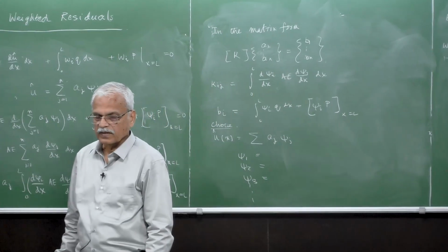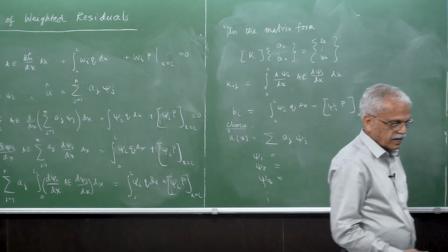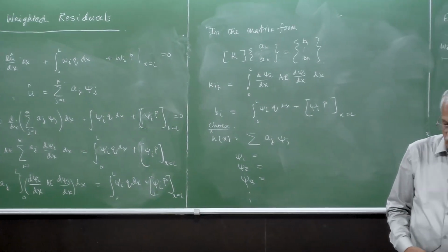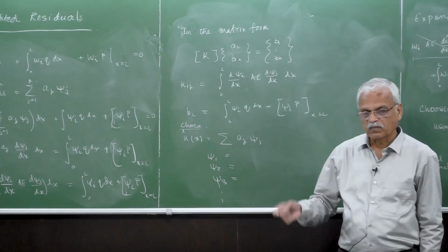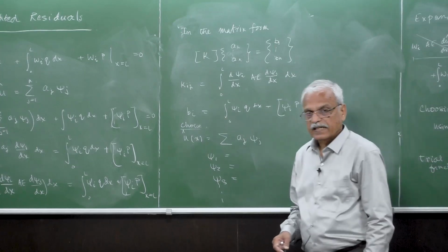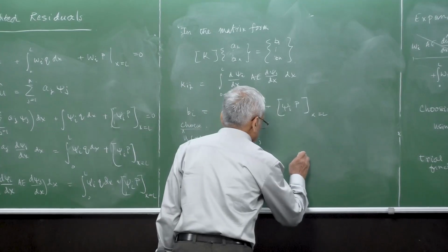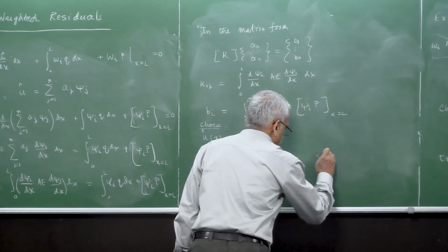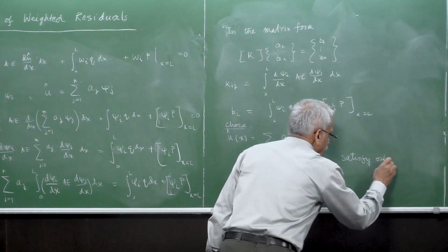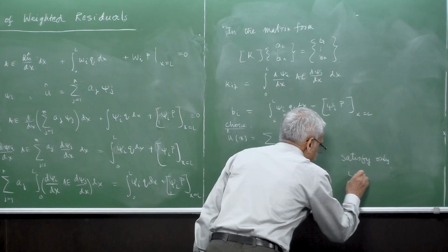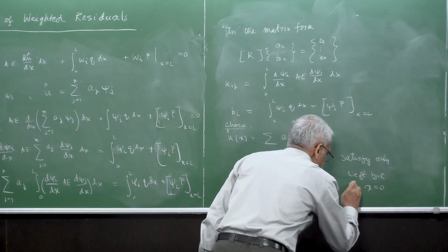Whereas on the right side, the applied force equals P. That has anyway been taken into the weighted residual statement, so we need not satisfy that. So this has to satisfy only the left boundary condition, that is, at x is equal to 0.